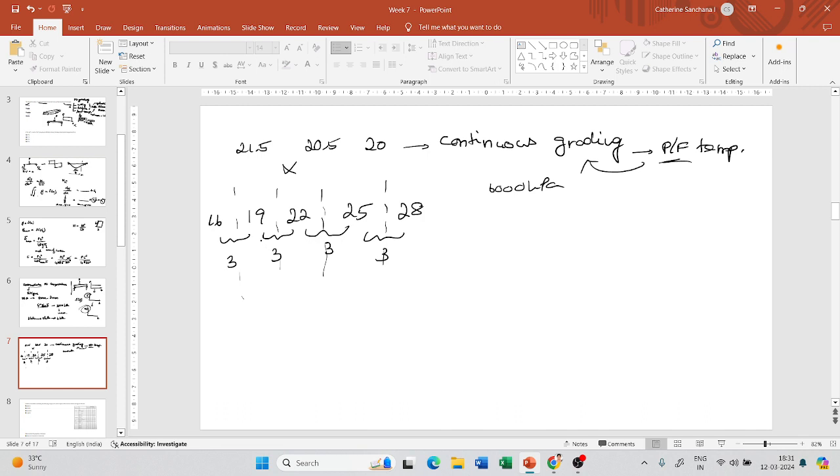But if you have to give the PG grading of bitumen, it should be one amongst these numbers, and the variation amongst these temperatures is 3 in the case of fatigue and 6 in the case of rutting, or high temperature, and low temperature cracking. High temperature grade and low temperature grade.